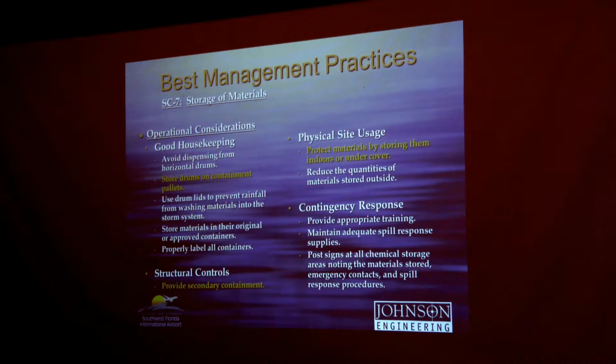Using drum lids to prevent rainfall from washing materials into the storm system, storing materials in their original or approved containers, properly labeled containers, reduce the quantities of materials stored on site or outside, providing appropriate training materials, maintaining spill supplies, and posting appropriate signage at all chemical storage areas.